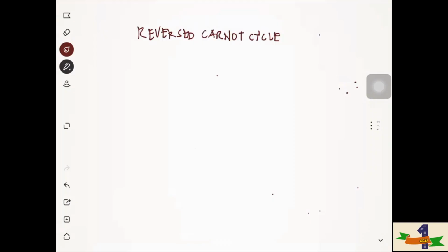To discuss the reversed Carnot cycle. Since the Carnot cycle is completely reversible, it is a model of perfection for a refrigeration cycle. There are two important concepts involving reversible cycles. One is no refrigerating cycle may have a coefficient of performance higher than that for a reversible cycle, which would be operated between the same temperatures of source and receiver.